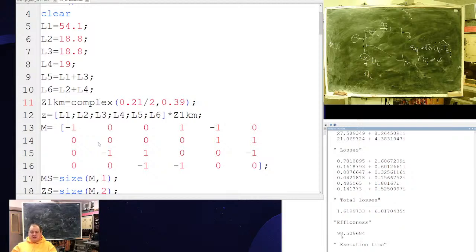When you compare them, you will see a set of charts like this which define extrema. This extrema gives you the best wire cross section for your line. But you need this tool to calculate losses, because you have two things to balance: construction expenses and cost of ownership.